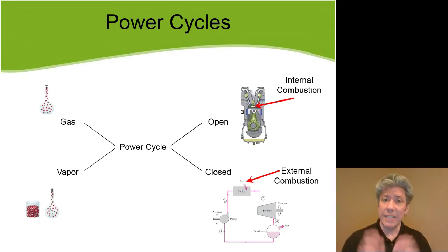Now, when we idealize those engines, we'll neglect the air intake and exhaust portions, because the whole purpose of that portion is really just to regenerate the working fluid. And what we'll do is assume that the fluid just stays inside of the piston cylinder device and that the piston cylinder device just remains closed. So we'll analyze it using closed system energy balances and so forth.